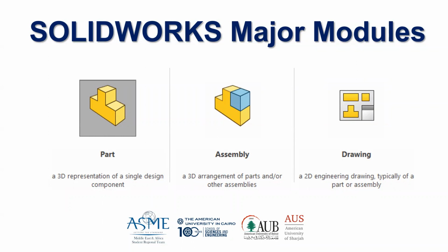This is very, very important. In the SolidWorks assembly module, we have something called mates. Inside this mate feature, you can use standard mates, advanced mates, and mechanical mates. So if you want to simulate or animate something like gear motion or screw motion, you can do it easily using the mates in this assembly module, okay?